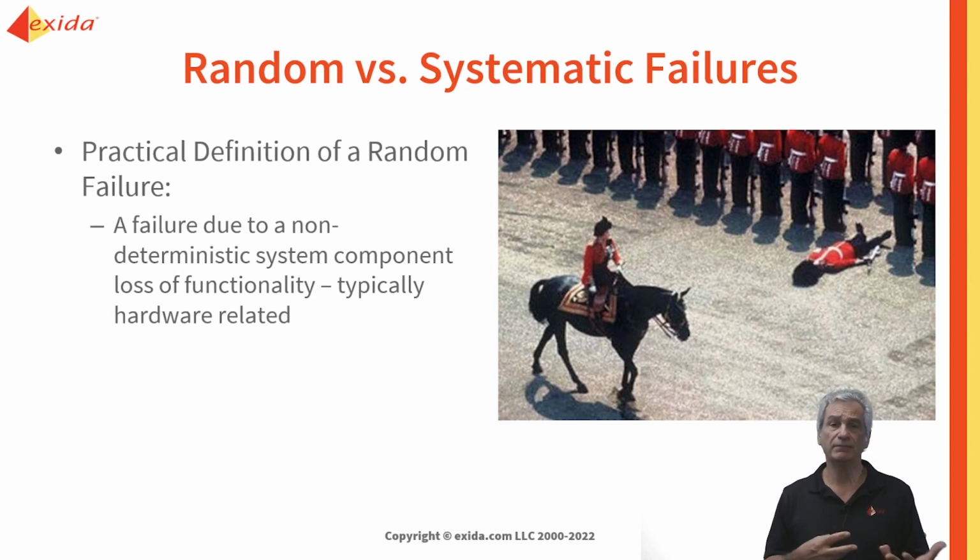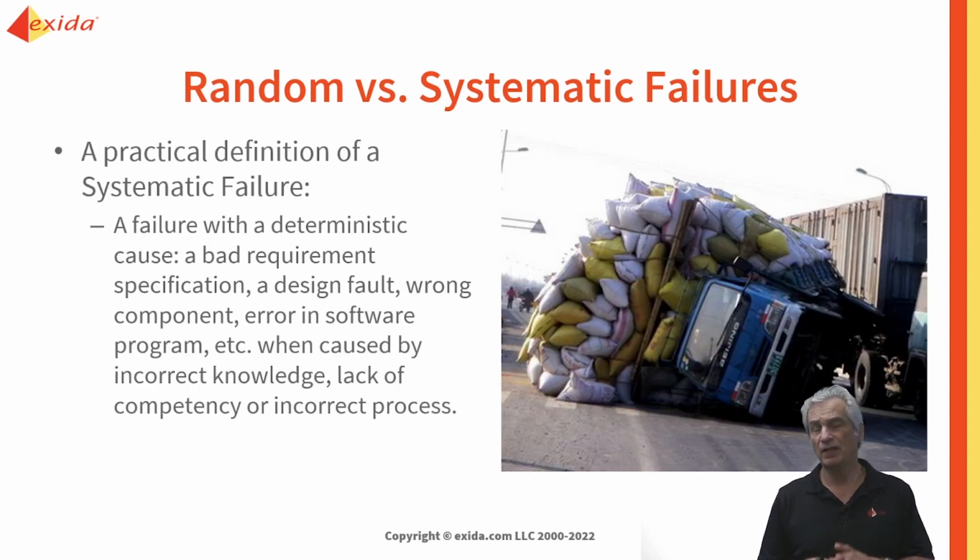And of course, when it comes to functional safety and probabilistic analysis, in other words, the calculations we do for our PFD average or our PFH, depending on whether it's low demand, high or continuous, these are all based around random failures. But the systematic is something that we don't always follow through on identifying and actually getting to root cause.